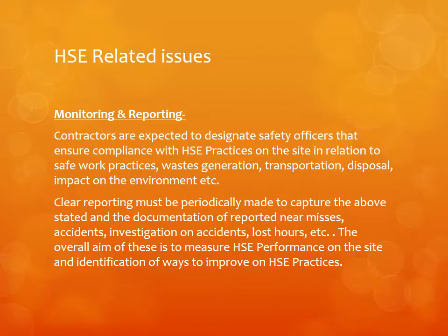Monitoring and reporting are very common and very important on every construction site. Contractors are expected to designate safety officers that ensure compliance with HSE practice on the site in relation to safe work practices, waste generation, transportation, disposal, and impact on the environment. Clear reporting must be periodically made to capture the above, along with documentation of reported near misses, accidents, investigation of accidents, lost hours, etc. The overall aim of this is to measure HSE performance on the site and identify ways to improve on this.